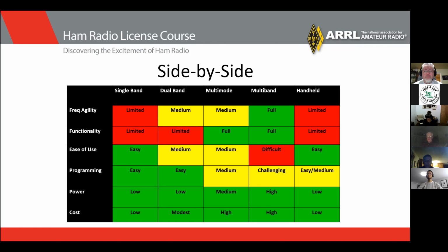And what we have done in our other classes is we've got one of those cheaper radios for $35. We give you an extra long antenna. What they call the rubber duck is about a 1/8 wave antenna. You actually need about a 1/4 wave antenna to transmit well. The longer antenna is about 19 inches long, and it transmits about 4 times better.